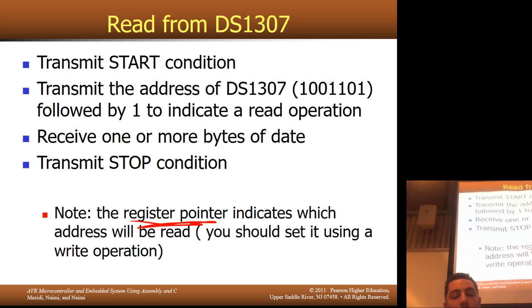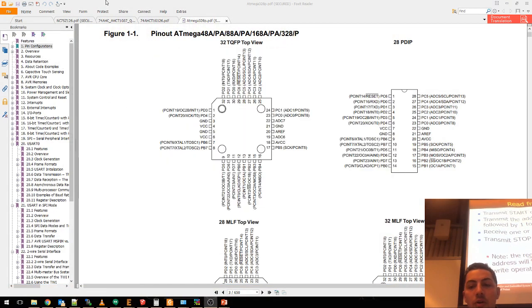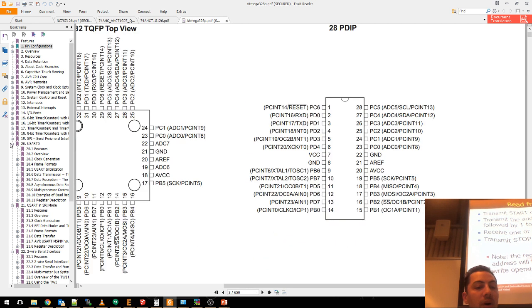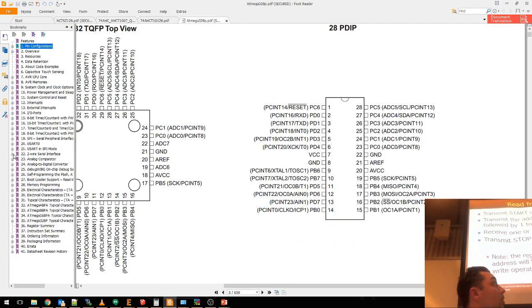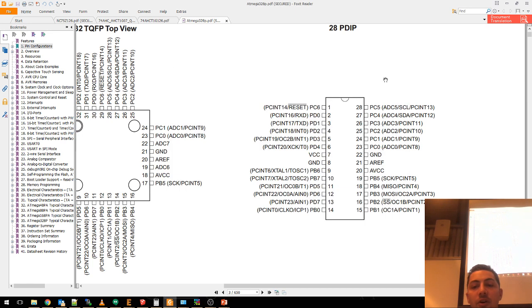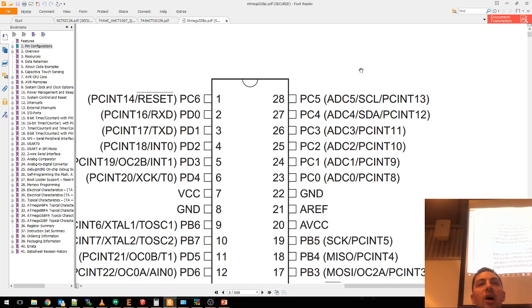Okay, so how are you going to go about approaching this design? Let's go to the data sheet. First off, you should consult the data sheet. First off, figure out where the SCL and the SDA pins are. That's important. You should go over and peruse. Oh, you can't see. You can't peruse. Full screen projector preview. There we go. That's better. So you should figure out where the SDA and SCL bits are.